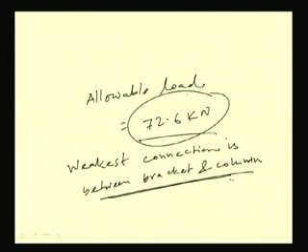So, when we connect a system of members through bracket, angle and girders, we have to see which one is the weakest, and the maximum allowable load will be based on that weakest connection. In that way we have to make it.